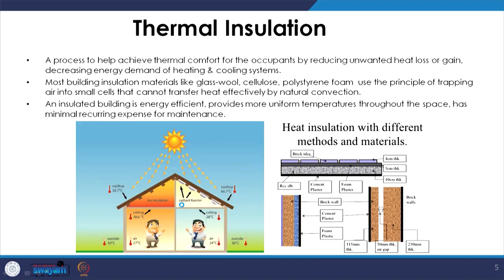So, when we are talking about thermal insulation, we are talking about adding a material which has an extremely low U value or adds a lot of heat resistance to the transfer of heat, and that is added to the regular building construction.